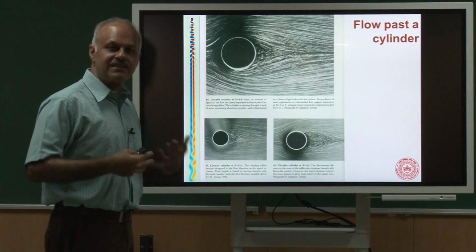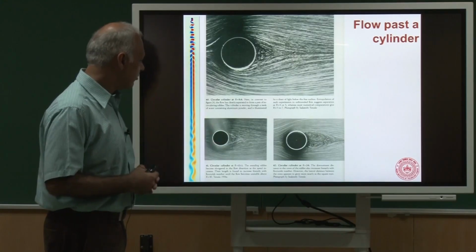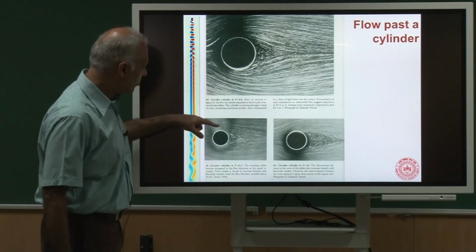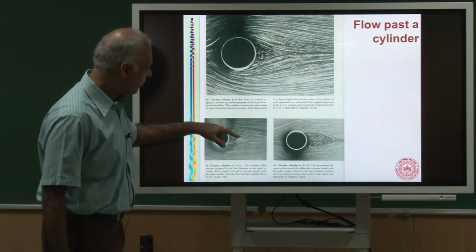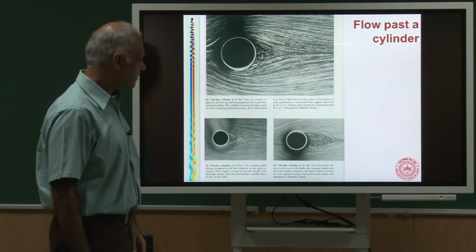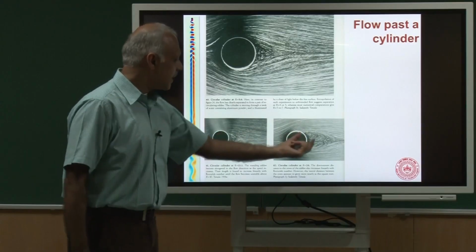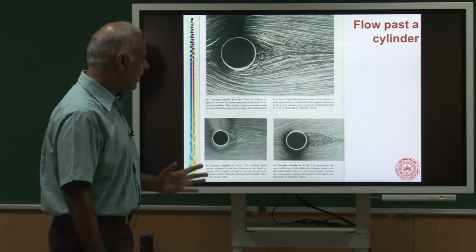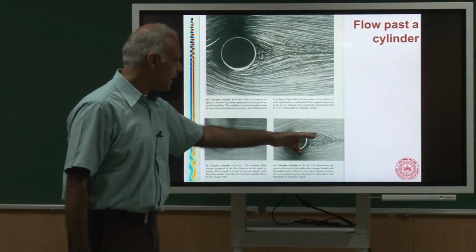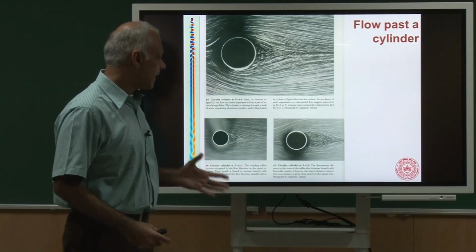Standing in the sense that they just stand there, just like you talk of standing waves in physics, you can talk of standing waves in fluid mechanics. So there are these little eddies which get stuck there. So fluid particles go not only around the circular cylinder, they even go around these eddies, and the flow in the eddies is, they just keep going in circles. And then if you increase the speed further, let's say about 26, then these eddies become larger in size. Okay. So far what has happened, I had a uniform flow coming in, and with increase in speed I get these two standing vortices which seem to increase in size, okay, as the Reynolds number increases.